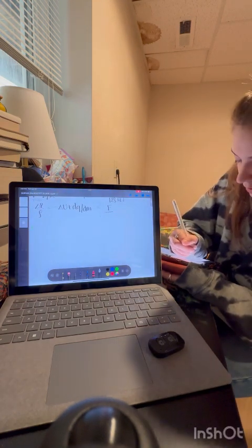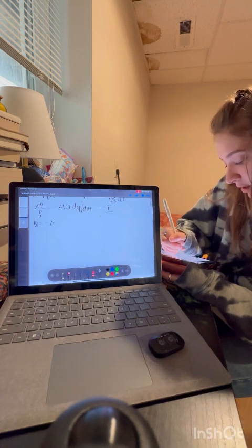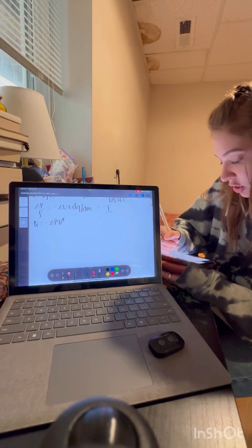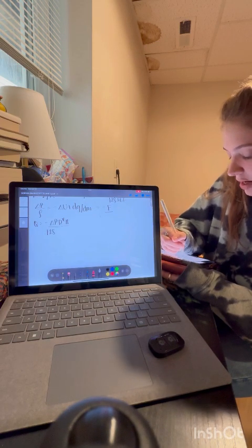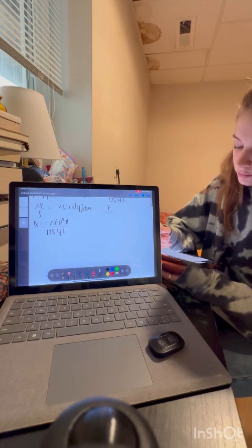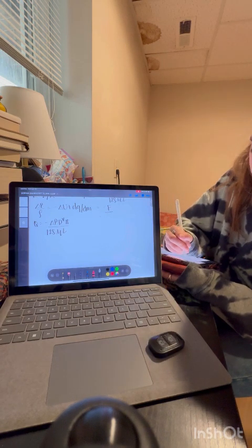If we look at Q being equal to negative change in pressure times diameter to the fourth times pi over 128 mu L, we will just move everything around to get here.